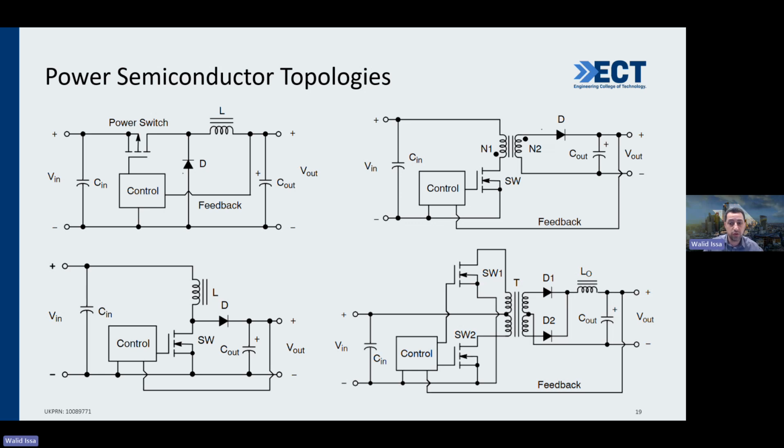So that's why we have to use the next one, which is the bigger transformer here with 2 switches, 2 MOSFETs, and 2 diodes to make the push-pull converter, for example. The left side one here is the boost converter that can be used internally in the electric vehicle.